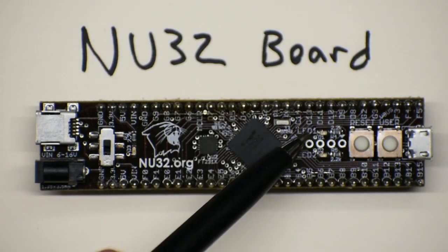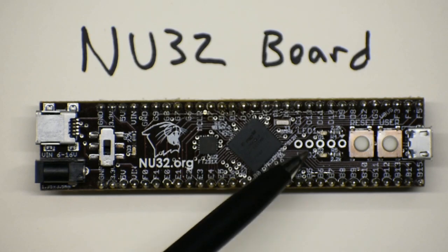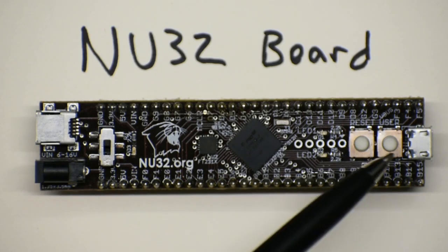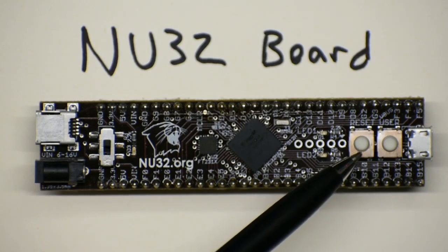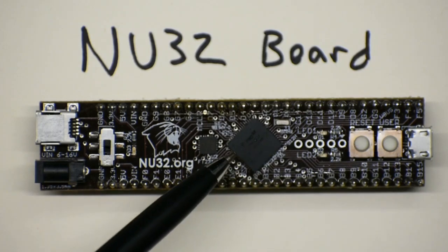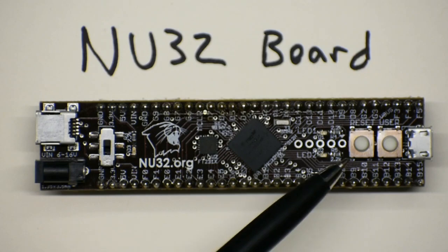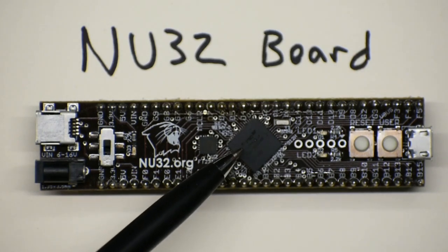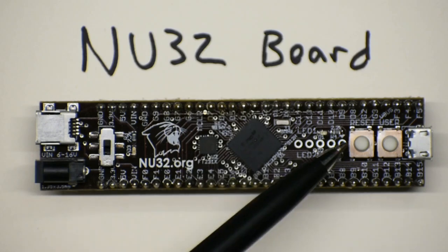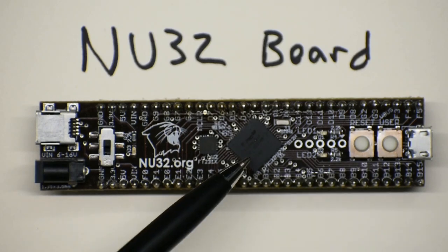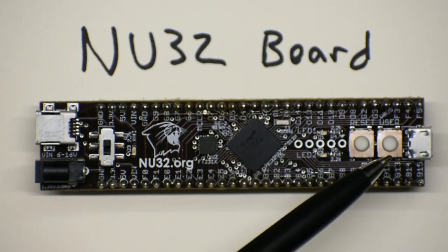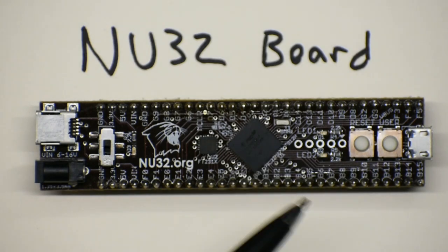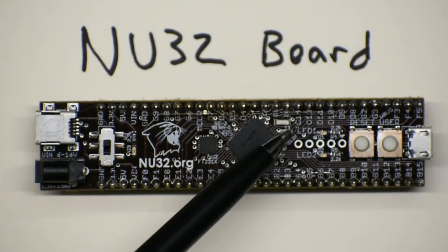It's got two LEDs that are labeled LED 1 and LED 2 built in, so we can immediately flash some LEDs without having to build a circuit. It has two buttons, a reset button and a user button. The reset button is hardwired to a reset pin on the microcontroller, so if you push that, the PIC stops whatever it's doing, and then when you release the button, it immediately starts the code over again. So that you don't have much control over that. But the user button is just wired to some pin, and so we can decide whether we want to read that pin or not.